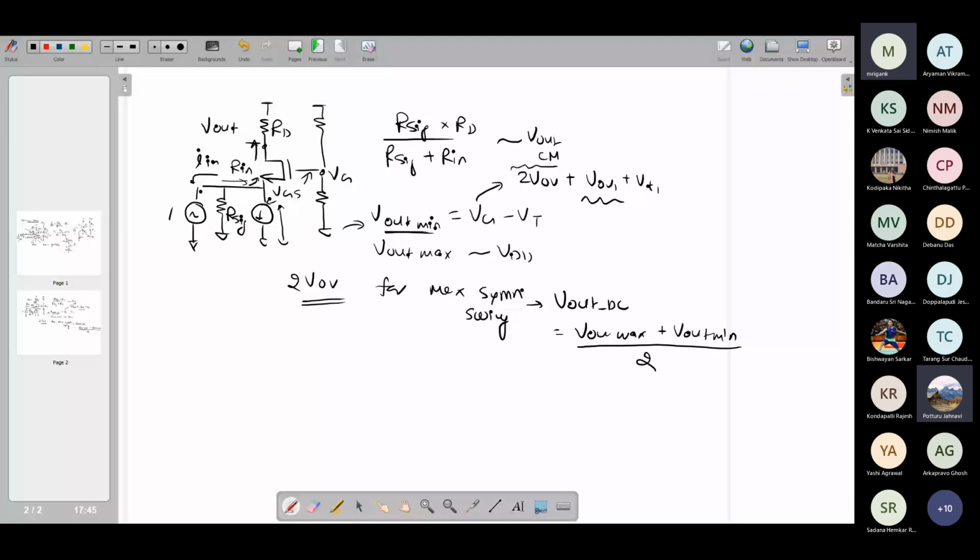So that means that as compared to the DC bias current, your current here is going up and down in both directions. So suppose you have a condition that the current is only going to sink current. That means if I assume that this is the direction of positive current, it is always either 0 or some value I in. So if it is unipolar, that means 0 to I in, it is only sinking current. This source is a sinking source where whenever the signal is coming, it is just drawing some current. It is never supplying current.